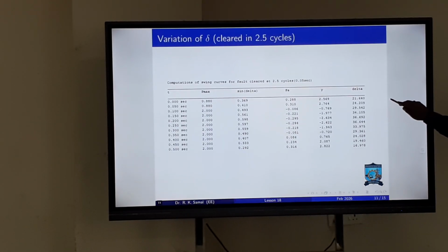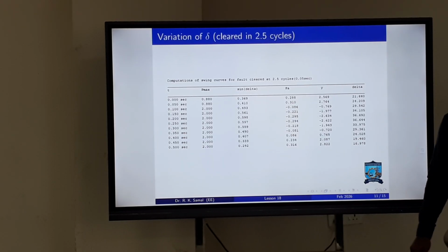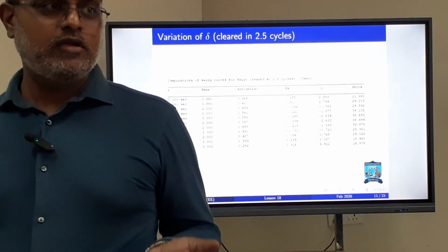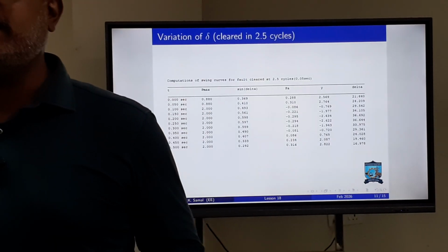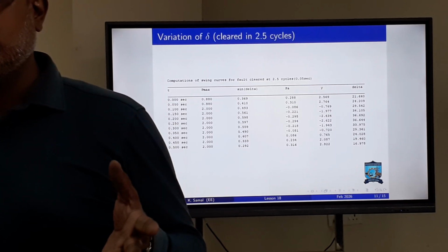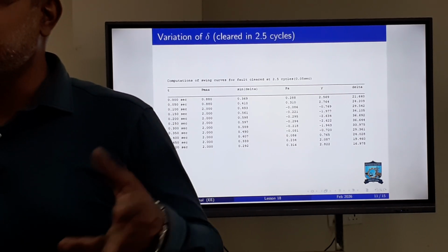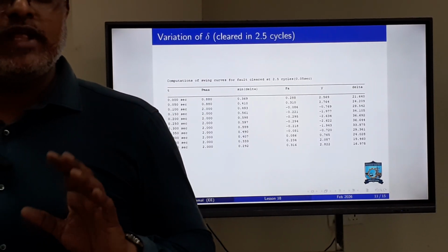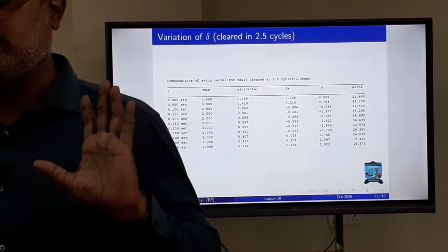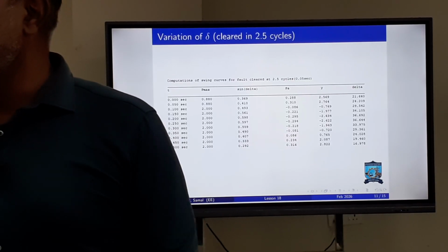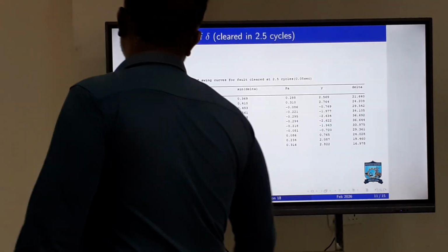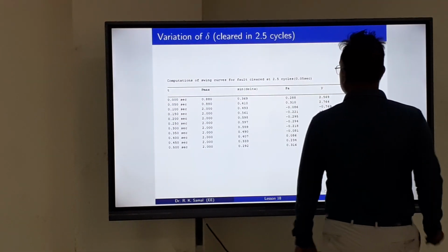So when you see the Scilab command line prompt, when you run, don't run the code on the command line directly. Save it as a file, put it in some workspace. Workspace means any folder you create, and inside that you put the file and run it. So that the command line is free for you to see the result. If you run that way, you will see all these excursions in the command line.